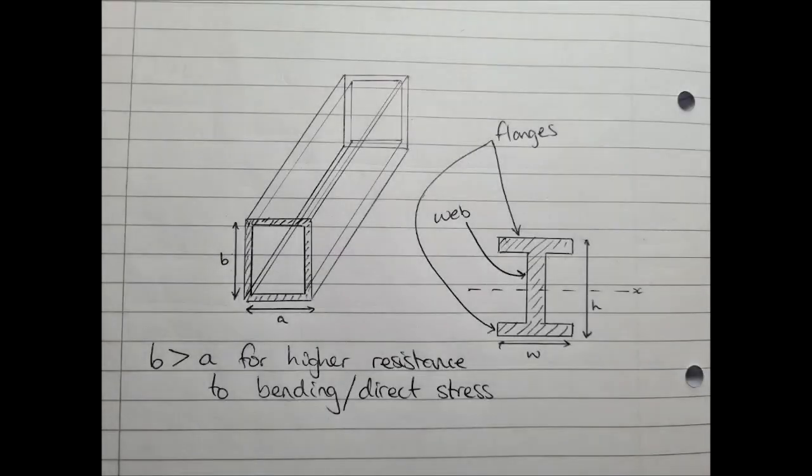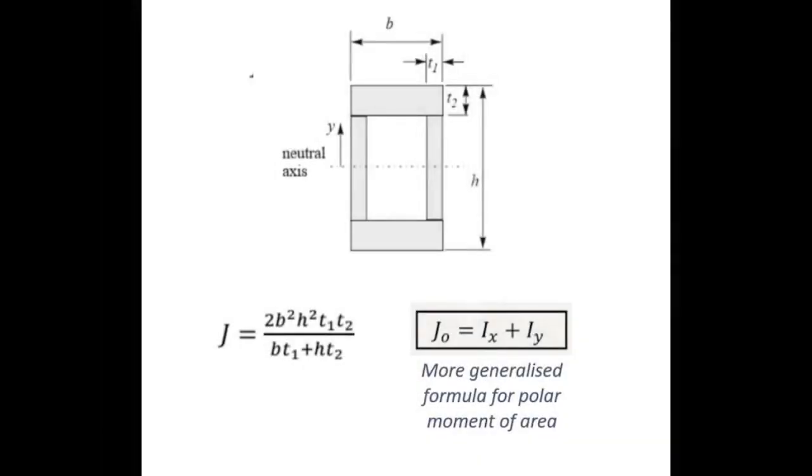Our initial concepts for the main spar were based on theory, allowing us to predict what designs were most likely to meet the requirements given. We determined through various statics equations that we needed a high moment of inertia and polar moment of area to lessen vertical deflection from stress and angular deflection from torsion respectively, both while weighing as little as possible.